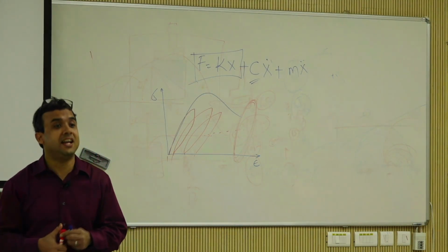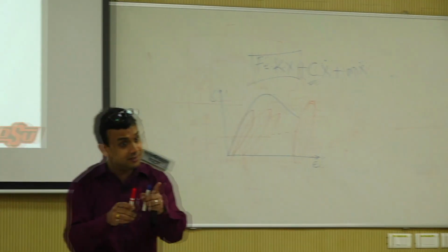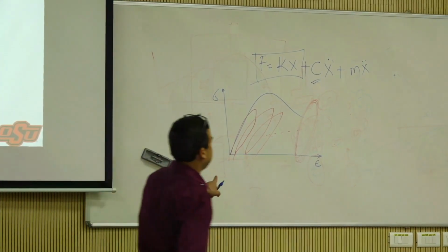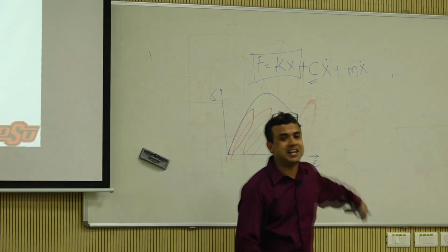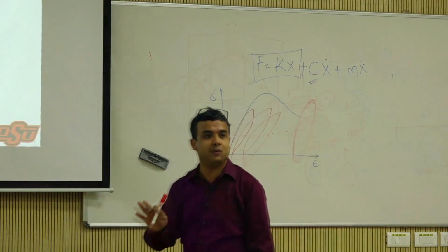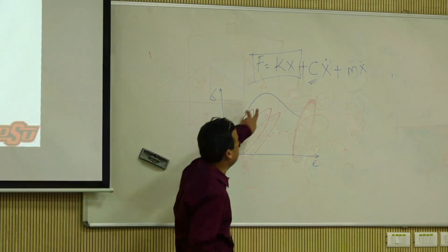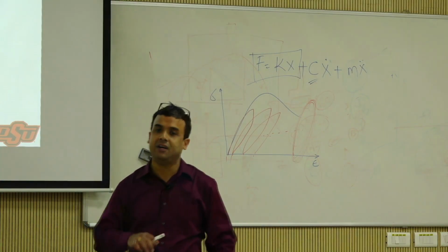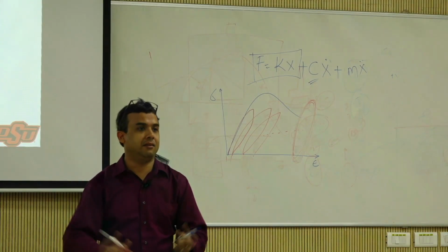So is resilient modulus an elastic modulus? Yes, but after a certain amount of plastic deformation has happened, and also it is something called a secant modulus, not an elastic modulus. We'll get into that. Why I showed you this is that all this behavior from now on, pretty much until the next 1.5 days, is going to be based on triaxial testing and triaxial behavior.